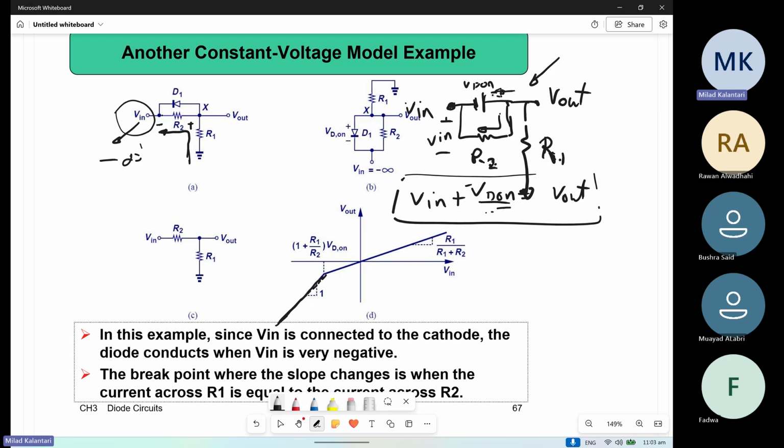Once the diode is turning off, it means the current passing through the diode is becoming almost zero, right? So all of the current going to the input is from the resistor at the transition point. The diode does not have much current; it's starting to turn off. Whatever is passing is through the resistor at that specific transition point.